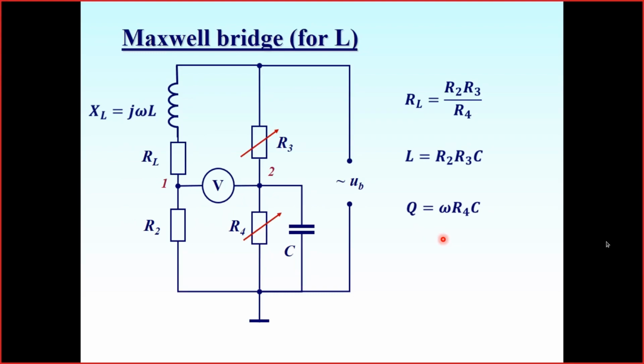Quite a similar situation, not absolutely similar, exists with inductivity measurement. With inductivity, the situation is even poorer. I have seen a resistor box many times, I have sometimes seen a capacitor box, but I could very seldom see an inductivity box. So it is preferable to have a measurement of inductivity where you don't need an alternating inductivity, and here the Maxwell bridge will help.